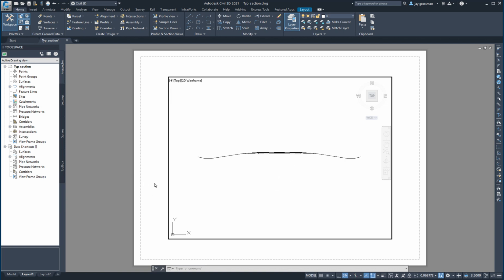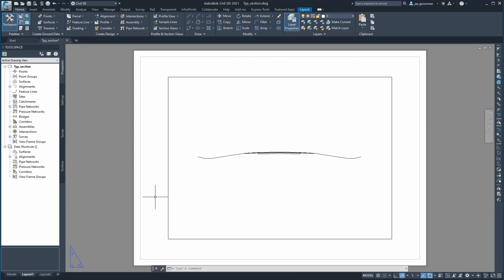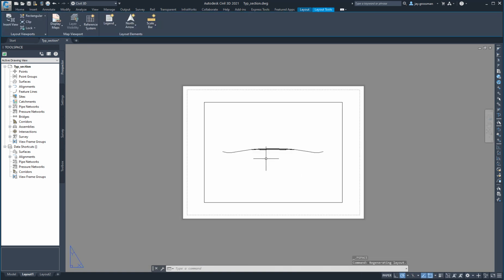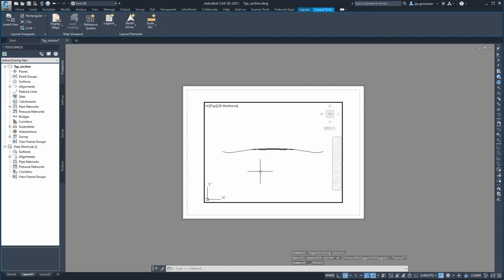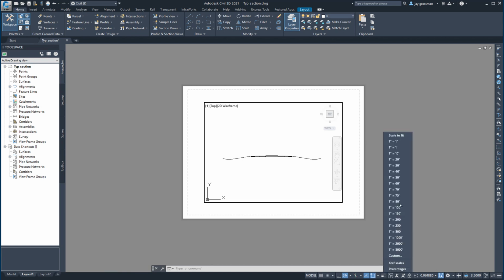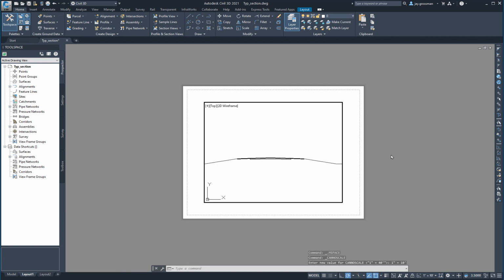And if I click out here, I'm back in paper space, and now if I zoom in and out, it zooms the whole paper, the whole sheet. If I double click in here and it turns into a darker, thicker border line, now I'm just zooming inside. All right. And I can set the scale here exactly by dropping over here. Maybe I want to do a 1 inch equals 10. Ooh, it doesn't fit. All right, so let's do a 1:20 scale.